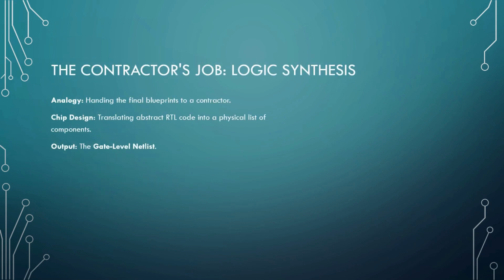Okay. Our blueprints are verified. It's time for the contractor's job, logic synthesis. The analogy is very simple. We are handing our final approved blueprints to specialized contractors. In chip design terminology, synthesis is a software process that translates our abstract RTL code into a physical list of components. The output is a crucial file called the gate-level netlist.